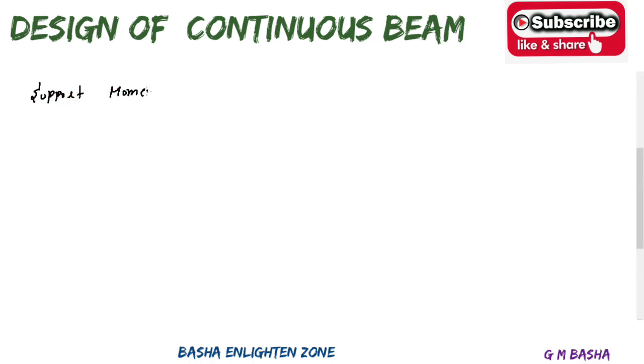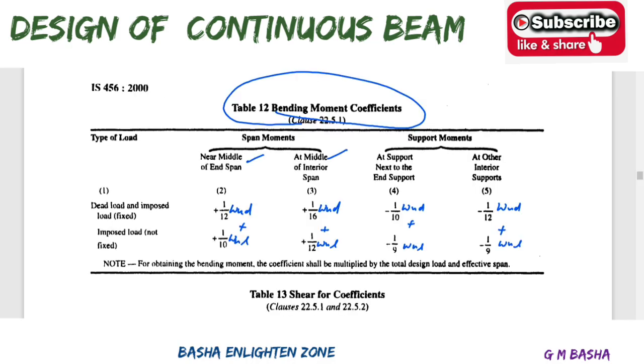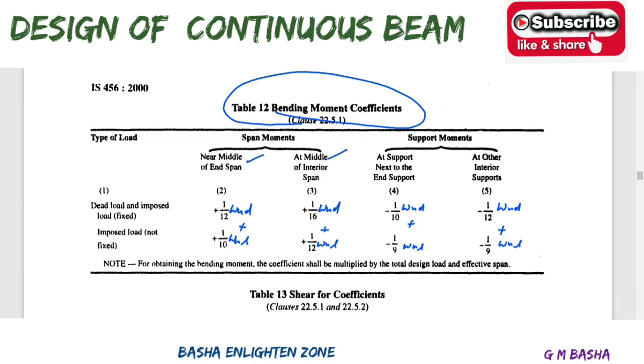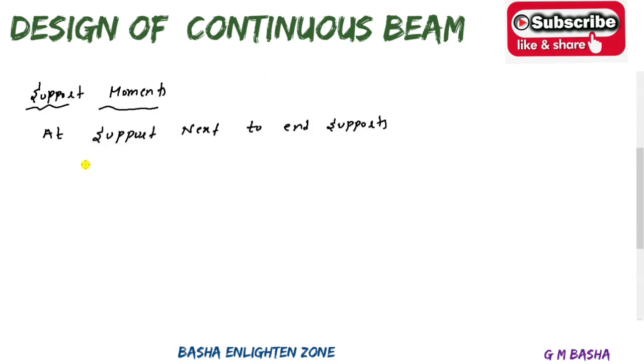Support moments. And again in the support moments, what are the headings? At support next to end supports. So what are the ranges here? Ranges will be minus 1 by 10 to minus 1 by 9.